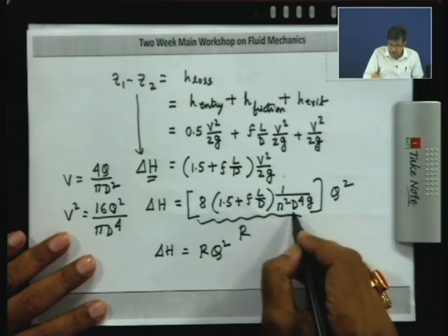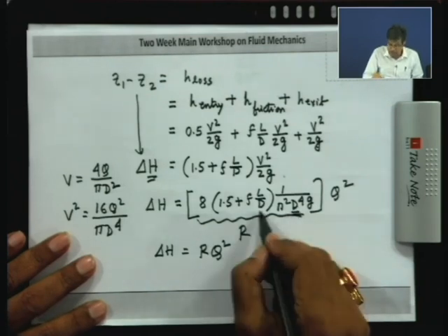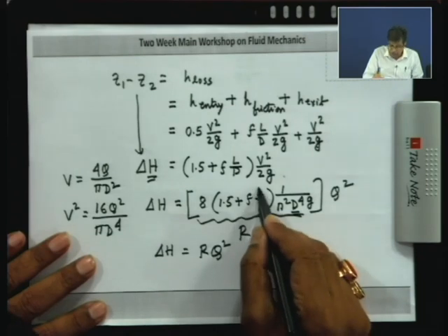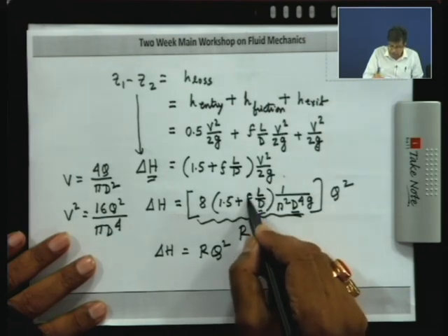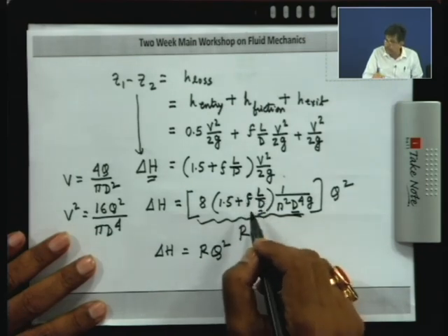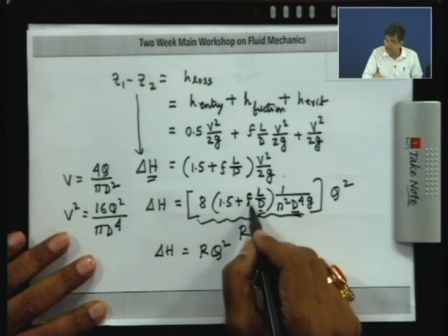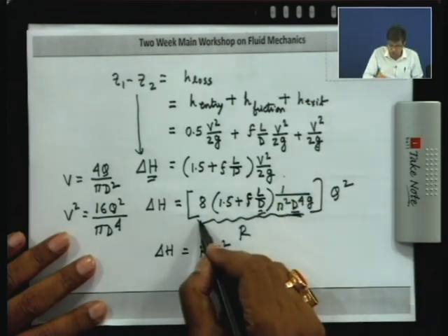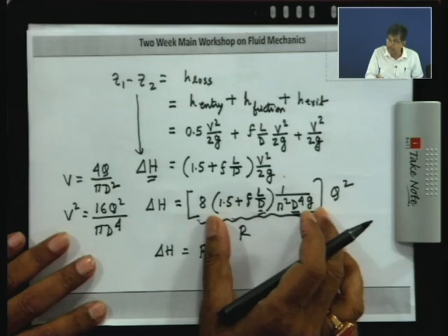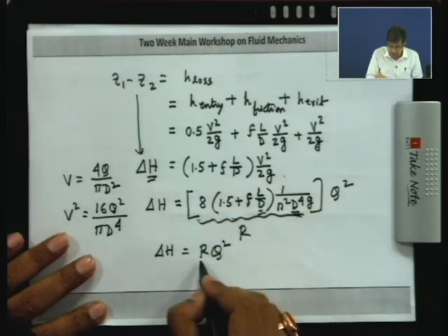If the diameter D is constant for the pipe for a given length L, it is given by a friction factor f. In case f is constant, independent of Reynolds number, in the high turbulent flow zone, this is almost a parameter of the pipe, known as the resistance.